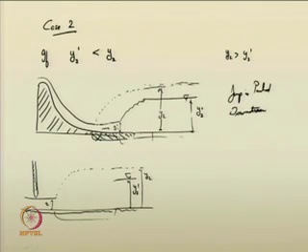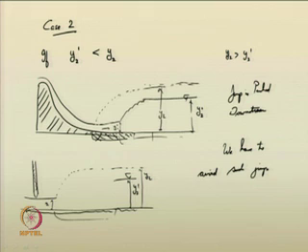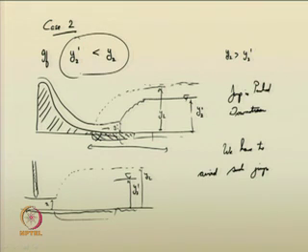So, we have to avoid such jumps, that is wherever the tailwater depth y2 dash is less than the sequent depth, you have to avoid such conditions, because such designs are not economical also. You cannot provide this entire reach as stilling basin, that will be too costly. So, you have to think on such strategies where to design the stilling basin appropriately. So, you can avoid such situations. These situations can be avoided if possible.